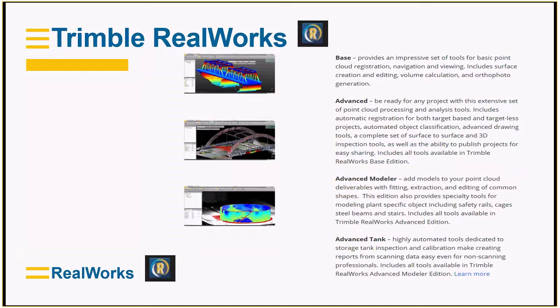There's 4 basic levels of RealWorks. We have RealWorks Base, which provides a set of tools for basic point cloud registration, navigation and viewing, and includes surface creation and editing, volume calculations and ortho photo generation. RealWorks Advanced includes automatic registration for target-based and targetless projects, automated